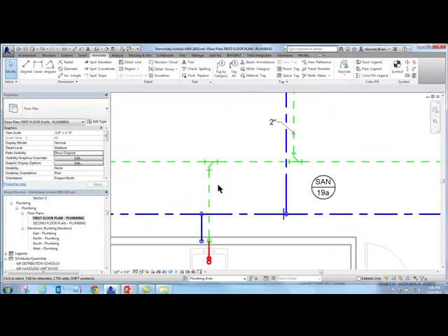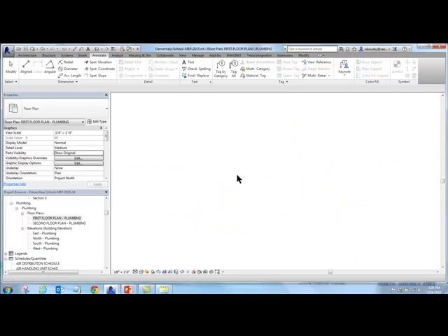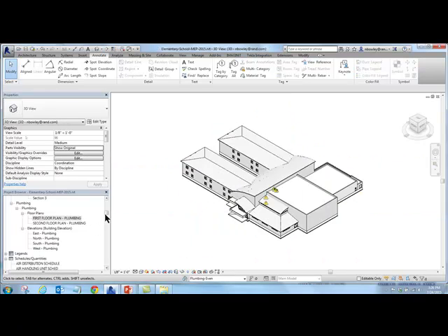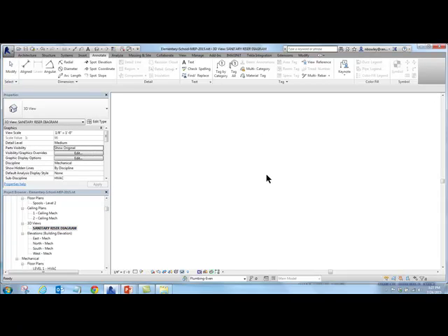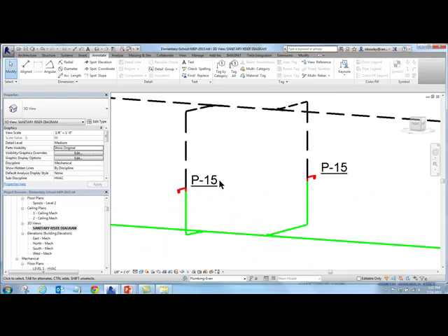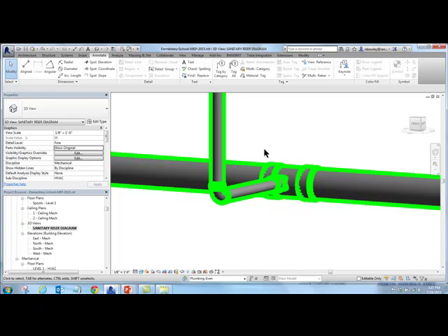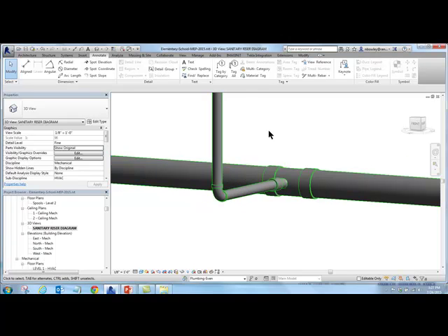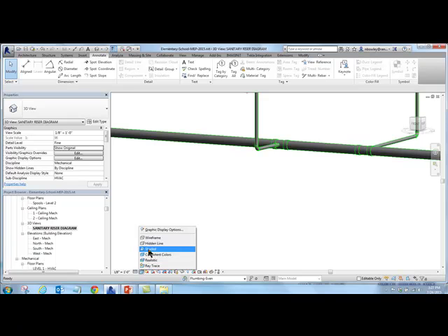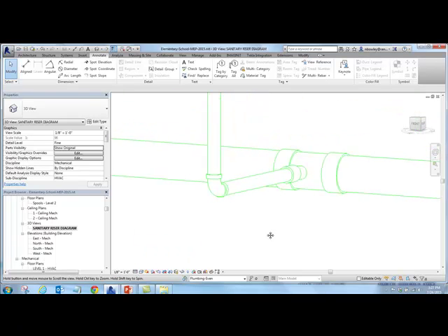All right, let's check it. Where the heck am I? Where's my riser? So this is at medium detail level single line, and at fine detail level, they're broken, just not with gaps. The gaps is kind of what I was talking about. So I put the TL. Now let's turn the shading off just so it looks more like what we'd actually do. So yeah, it doesn't break with gaps, I guess is what I meant to say.